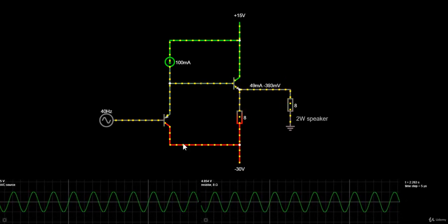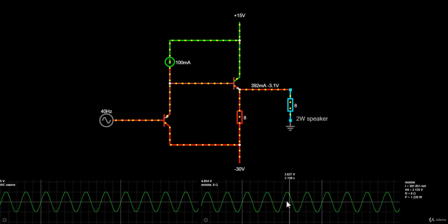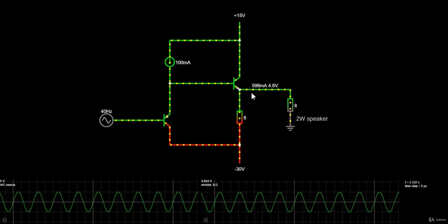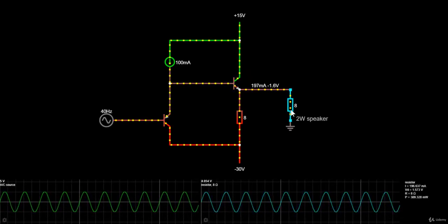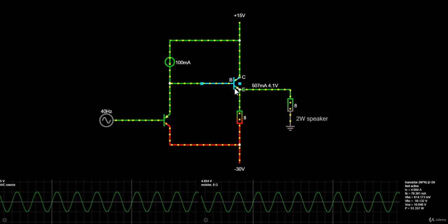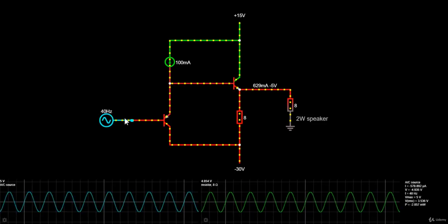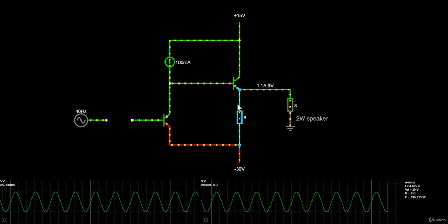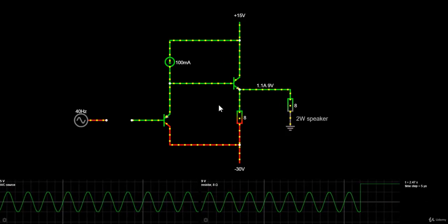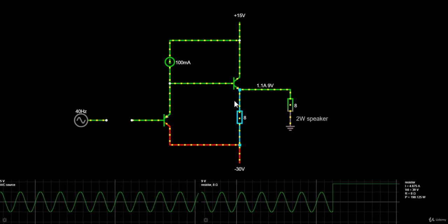Alright, so in the last course we have talked about the circuit, right? Even though this circuit is not amplifying in voltage, since it's an emitter follower, it's very good to use in cases where current amplification is required. The problem of this circuit though was that the active device, which is the transistor, is in conduction all the time, especially when there is no input signal present. This never turning off feature of this amplifier causes a reduction of power efficiency, which means nothing else but a lot of power is wasted for nothing.